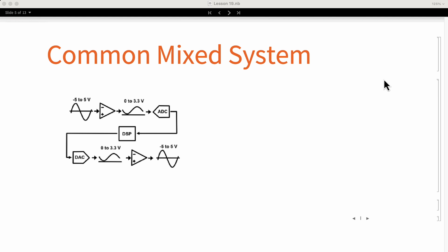In the diagram, you can see an overview of the system. In the synthesizer circuits that I made, it is common to have voltages that go typically from -5 to 5 volts. The analog to digital converters cannot take these relatively high voltages. It needs a signal that goes from 0 to 3.3 volts. Any signal outside that range is clipped.